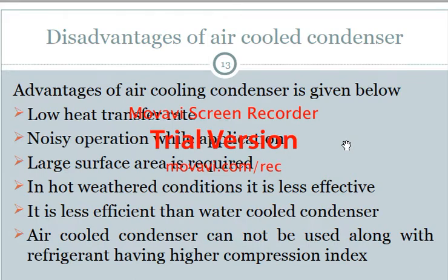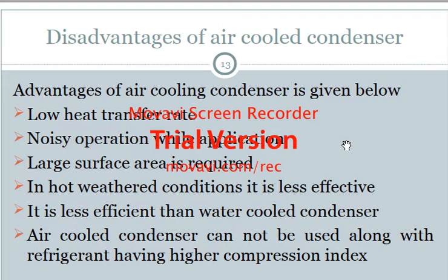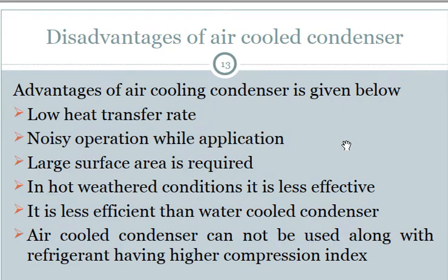Low heat transfer rate, noisy operation while in application, and a large surface area is required. In hot weather conditions it is less effective, of course, because we use environment air to cool the refrigerant. So what happens if in summer we supply hot air to the condenser? Maybe not effective, of course.